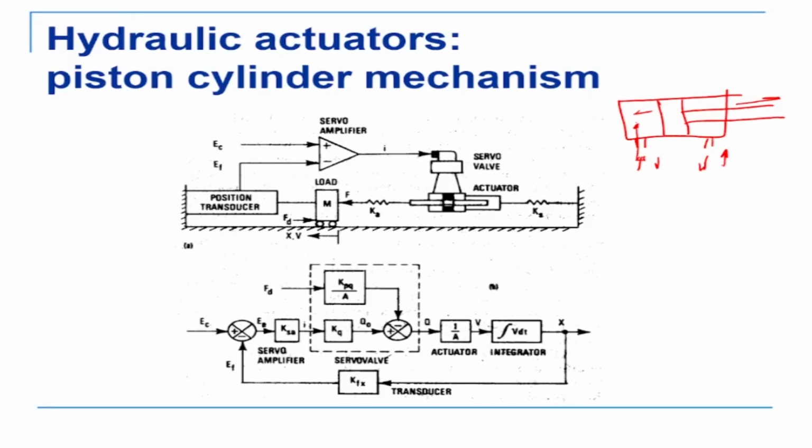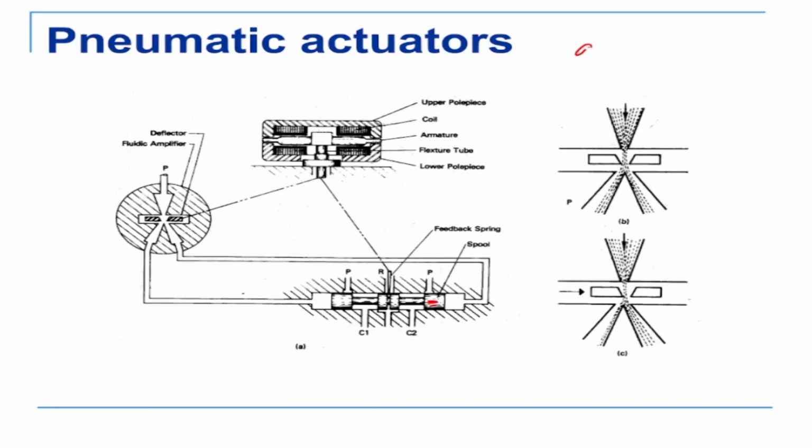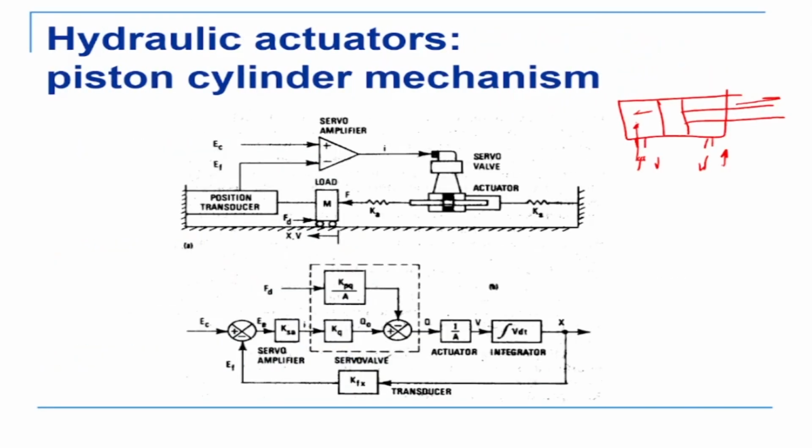Okay. So these are piston cylinder mechanisms which are mainly used for grippers. Okay, robotic grippers are very often piston cylinder mechanisms, and they are pneumatic. Okay, now the next is smart actuators. Now, electric motors, hydraulic piston cylinder mechanisms, pneumatic piston cylinder mechanisms, they are conventional actuators. Okay, which means that they suffer from the size effect.